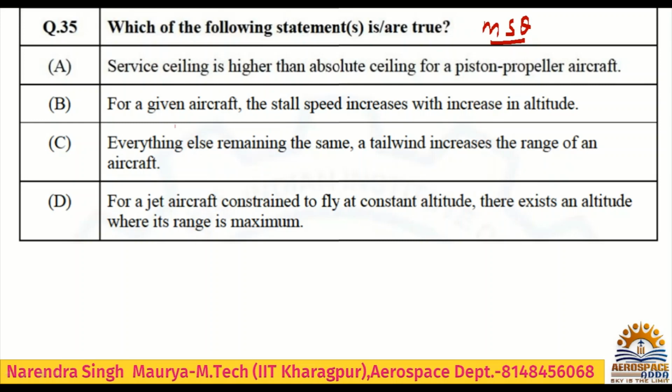Anyway, which of the following statements are true? Service ceiling is higher than absolute ceiling for a piston propeller aircraft. No, this is completely wrong. Absolute ceiling is always greater than service ceiling. All right. For a given aircraft, the stall speed increases with increase in altitude.